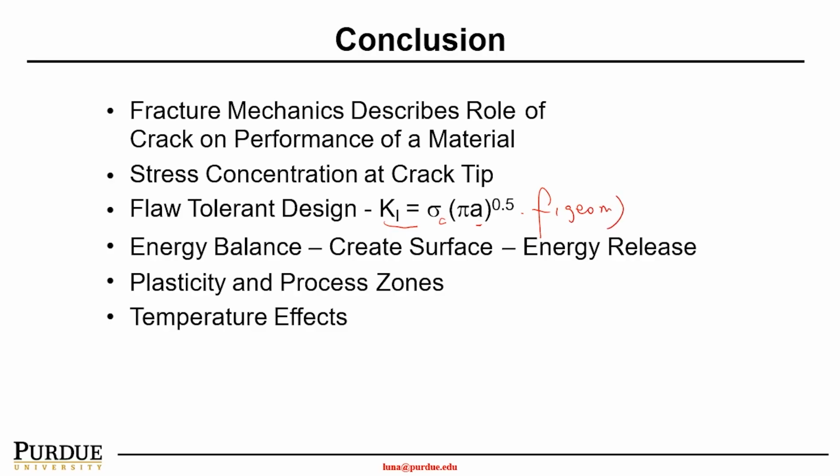And then we discussed the Griffith theory from the energy balance standpoint. The energy needed to create the new surface should be smaller than the energy release rate.